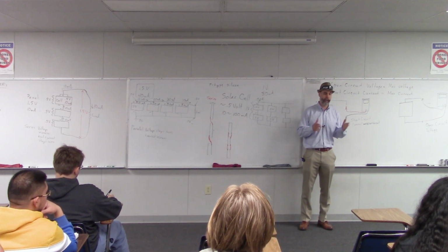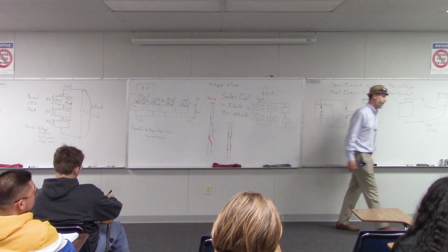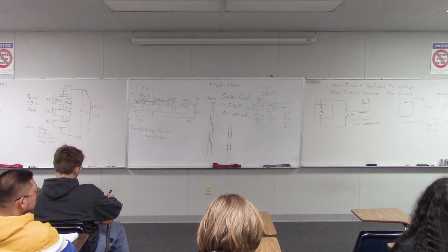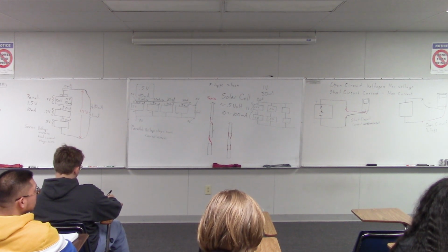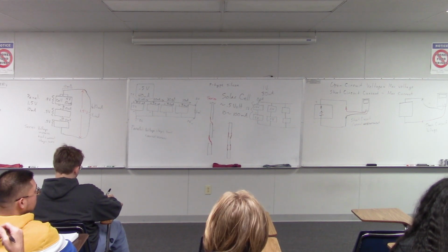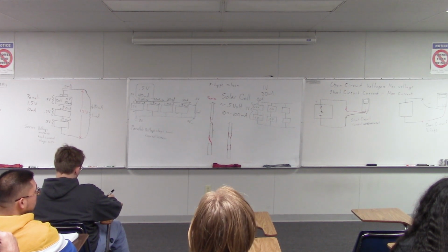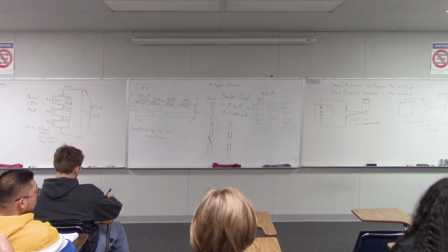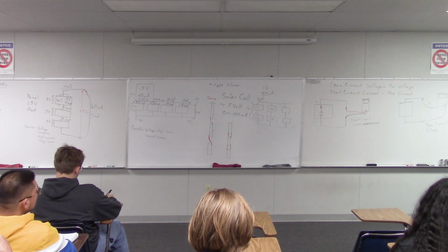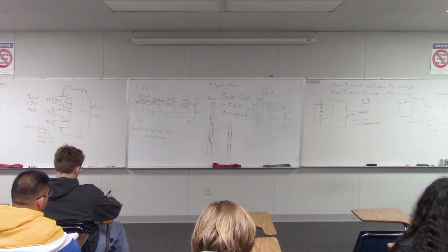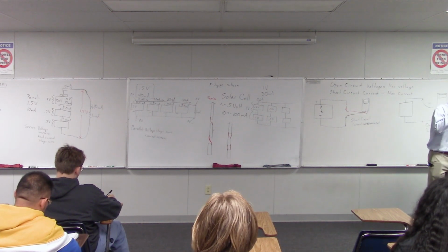One of the most important is the angle. So if I have this meter and it's up here and it's pointed straight at the light, I'm getting about 13 watts, 14, something like that. If I start to turn it, if I'm at a 45 degree, now I'm at 7 watts. Just that much angle gives me 7 watts. Over here, I'm down to 4 watts. And then pointing sideways, I'm at 1 watt. So the angle makes a big difference.